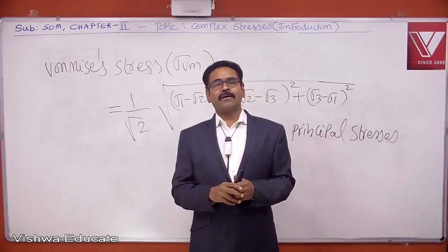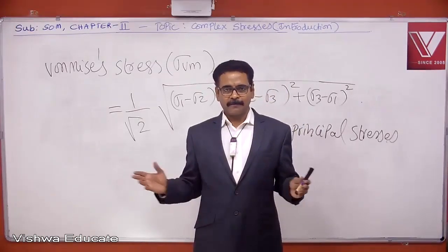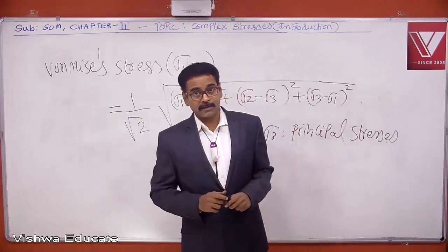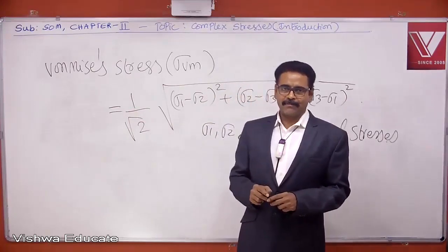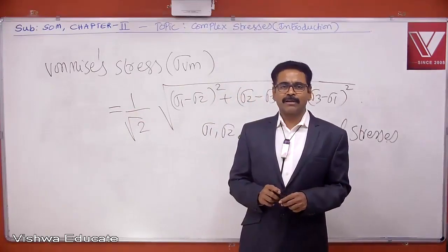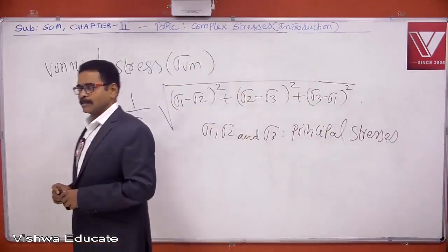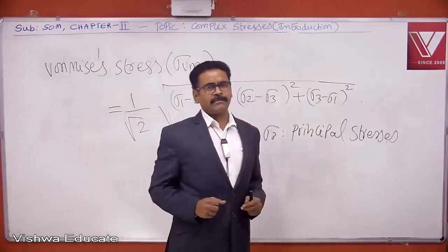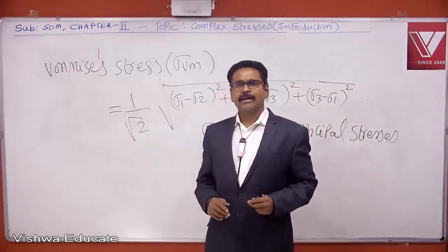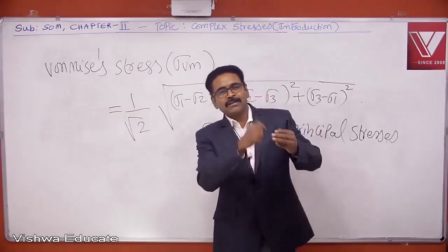What will happen to the car? What will happen to the driver? We have to run a test like this. While conducting this crash test, we may measure several parameters. One of the parameters is the actual failure stress, the actual fracture stress. In actual condition, at what stress is a component breaking? Not in the laboratory, not in theory books.